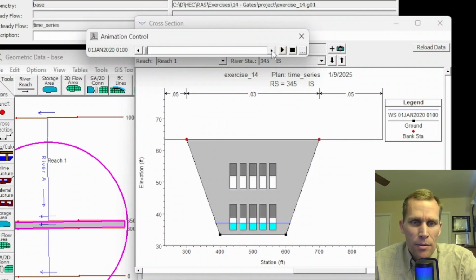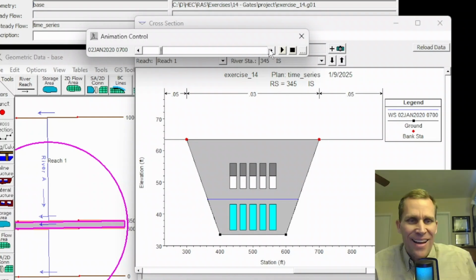So we're starting at 0 flow, and then right about here is 5,000 CFS. It's holding steady. Now it's increasing to 10,000 CFS. Now, okay, so what just happened was we passed the 28-hour mark, and the lower gate group opened up completely, and hence the water surface dropped because it can now flow more through this lower gate group. Okay, I'm going to continue on now.